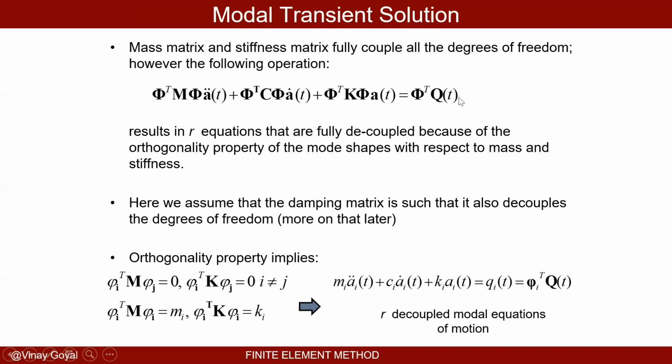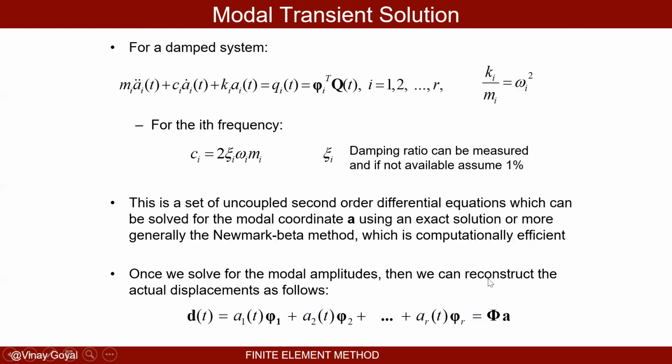Notice how Q bold here is a function, and that's a forcing function here. And so this multiplication just gives you a Q_i(t), which, you know, that's what's changing over time. Another important consideration is that K_i divided by M_i actually happens to be the frequencies of the system, omega_i squared. So not only can we, we know what the eigenfrequencies are. So I know what this is.